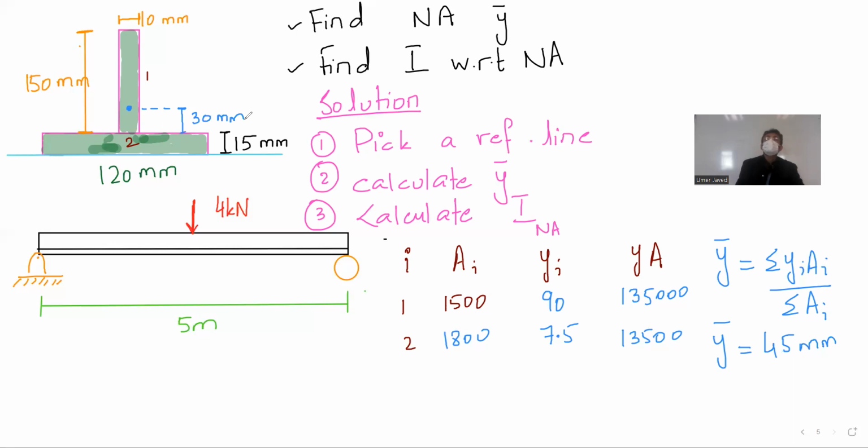I will again emphasize, from the beginning I have said this, nothing has changed. The neutral axis goes through the centroidal line, for sure. For a rectangle, your centroid used to be in the center, so our neutral axis used to be in the center. Okay, life is beautiful, I guess. Now we will calculate the I.